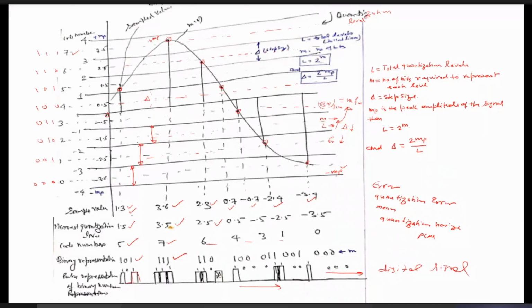It means PCM will require a large bandwidth to transmit, which also has certain restrictions. The bandwidth constraint is very important, which we must consider. So we cannot keep increasing the value of M. You cannot think that M is in our hand and we can increase it to any level. It also has a constraint on the bandwidth.